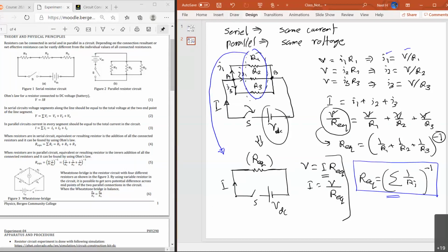And from that angle, we can calculate the effective resistance too, by knowing the voltage and total current passing through the circuit. So that is called measured, right? Technically, I can say R equivalent here is equal to V given divided by the I passing through the circuit, right? So this is what we call the measured value.